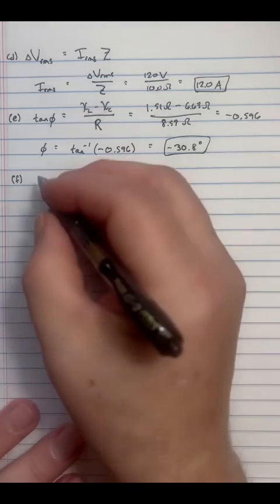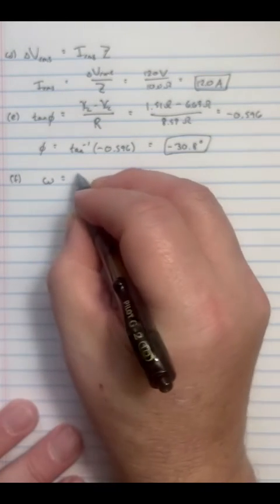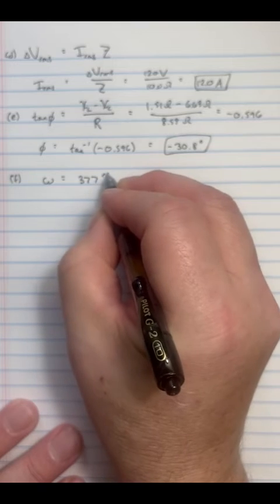Well, we have a similar sort of thing here. If we set the source of voltage's frequency to the resonant frequency, we can maximize the input of the circuit. We get the most bang for the buck, so to speak. So again, something we might want to know. So just to remind ourselves, earlier, the actual frequency that this circuit was using is this.